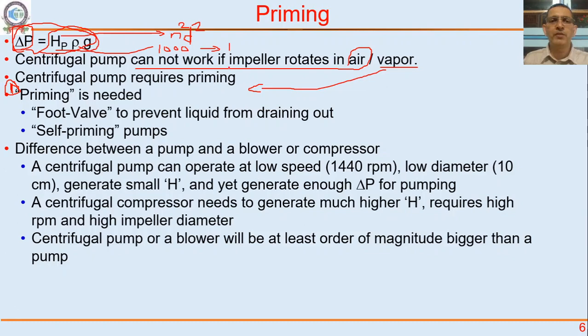So centrifugal pumps require priming. And how is priming done? Let's say it's a water tank in our building. There is a foot valve that prevents the liquid from going down into the storage tank below when the pump is stopped.